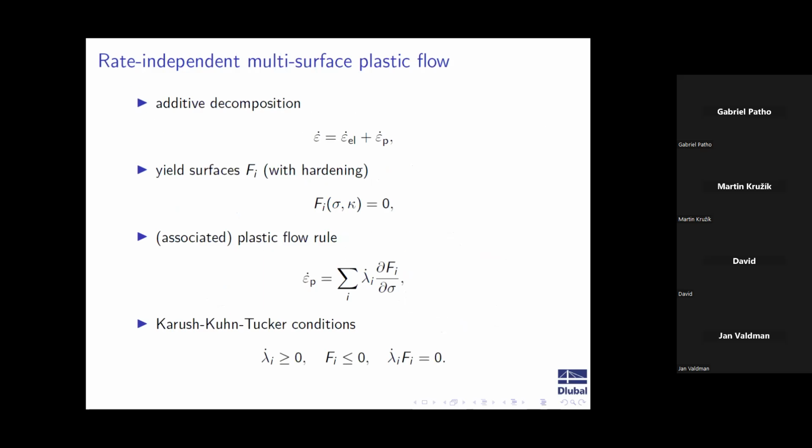So that's for notation. We will need to go into plasticity theory, with very, very basic assumptions. We do not need to go very, very deep. Some additive decomposition of my infinitesimal strains into an elastic and plastic part. We do need to consider multi-surface plasticity, so we can have different or more yield surfaces, which I denoted here, capital Fy.